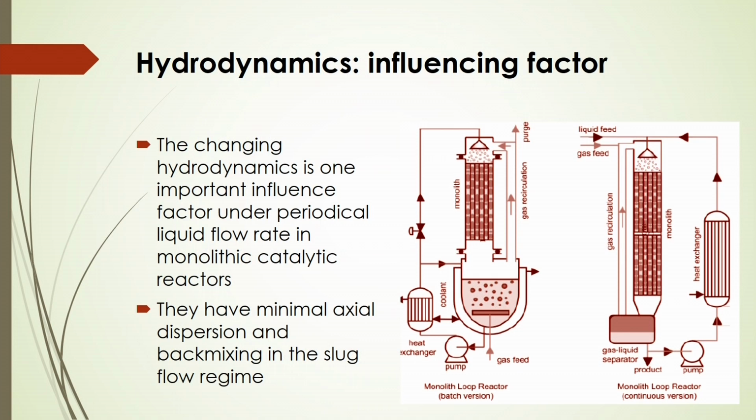The slug flow regime is one of the important flow characteristics there, because for the microchannel based reactor only this type of slug flow regime can be obtained, where you can get minimum back mixing of the fluid phase.